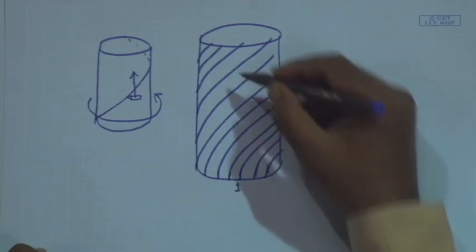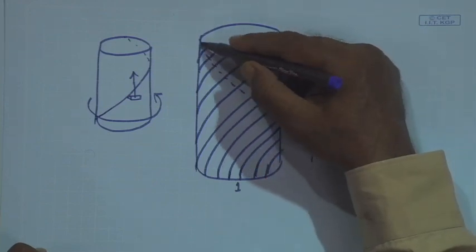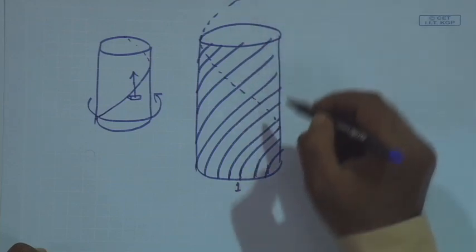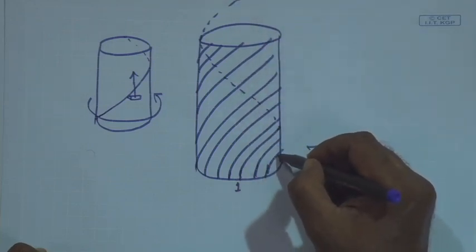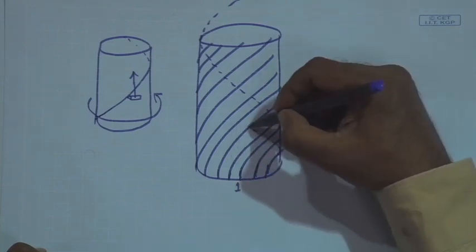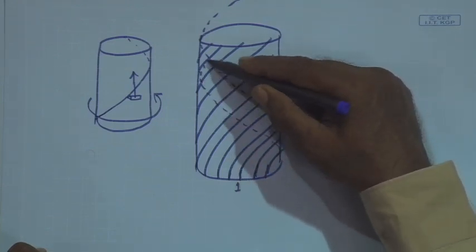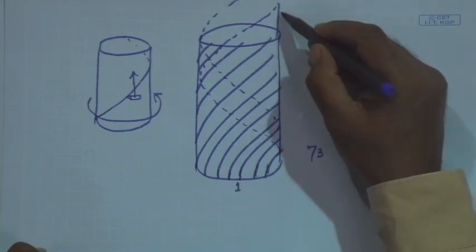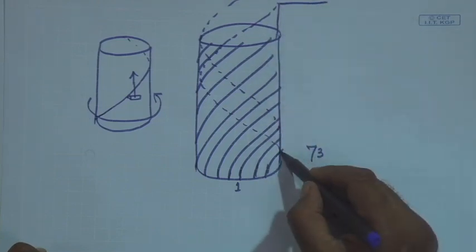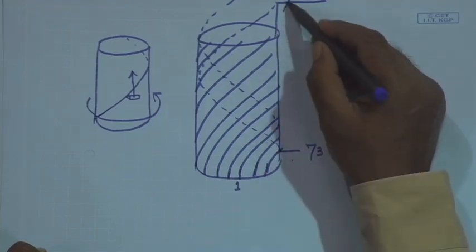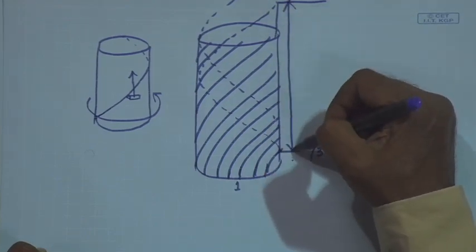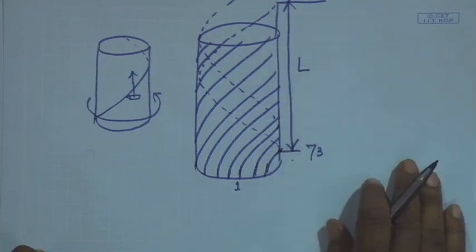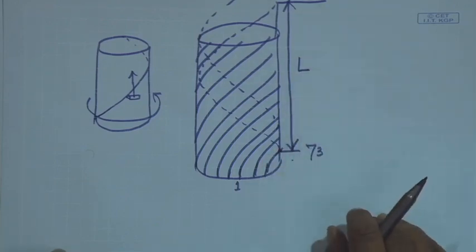Okay. So each of these is an individual helix, and therefore, say if you name this one as number 1, this climbs up this way, and just imagine what distance it is going to climb up. Sorry, we have run out of space. Let us take this one. This seems to be more obedient to our needs. Fine, that is it. So, it has come back to the same position, and this is equal to the lead, the climb up in one rotation.